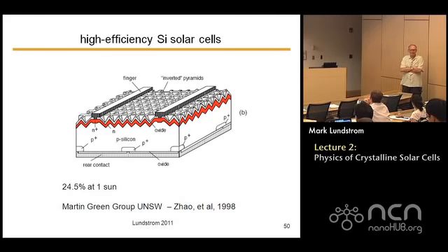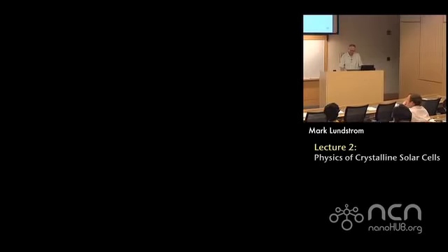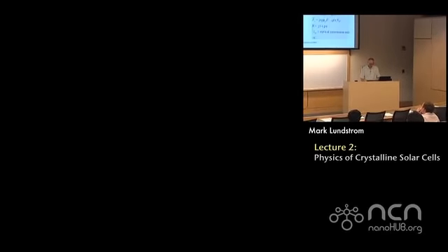Okay, we have another question. In describing the recombination in the space charge region, why does it go as just n over tau and not a product of n times p, because it depends on both concentrations? Does it come into the thing that you're talking about with the lifetime? Is it just a simplification?